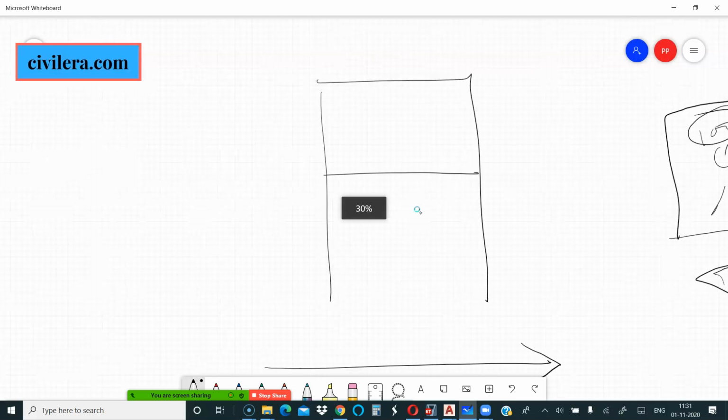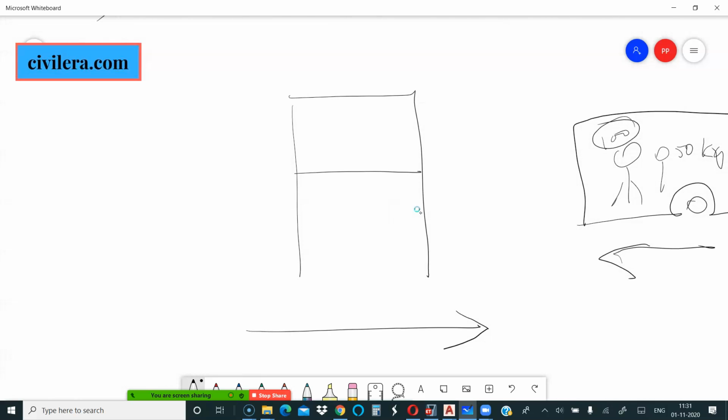In the same way, when you have a building and the ground moves, the building experiences inertia. The taller the building, the higher the CG, and the more the mass, the more inertia. So if you have two identical buildings of the same height in the same region experiencing the same earthquake force, the one with lesser weight is going to have lesser seismic demand, because the heavier one will have to take care of its heavier mass. So as a structural engineer, it is always advisable to reduce the weight. Encourage others to use lighter things.